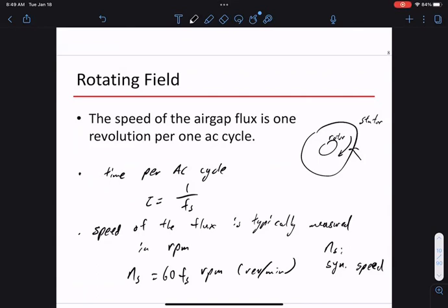So how do we slow down the synchronous speed of the induction generator? There are ways to slow this down. I want to make the gearbox life a bit easier, not to convert it to 3600. Remember from 351, how do you lower the speed? Increase the number of poles of the rotor.